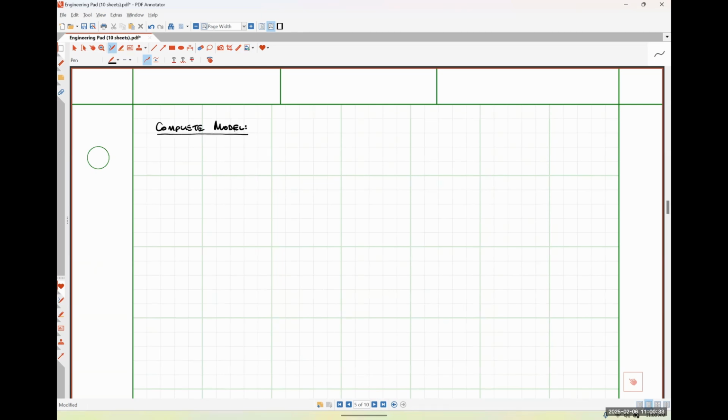So this is a model with the entire circuit now operating at a frequency of F sub S. So everything is essentially working at stator frequencies. We're not concerned about our electrical frequency of our rotor anymore, okay? So our circuit model is going to be something like this. So here is the terminals that we apply our input power to. Working on the stator side of things, here is our stator resistance, our stator reactance.